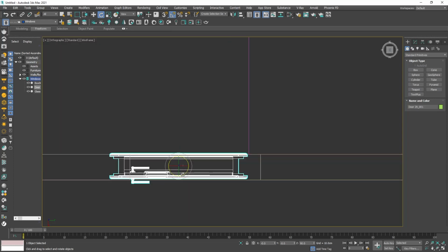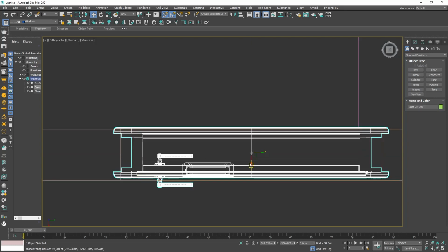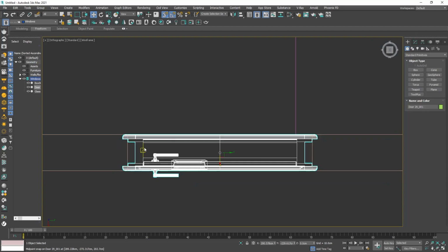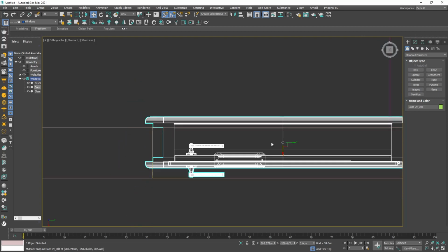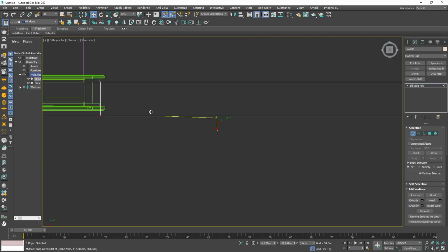Unfortunately, the door width is not the same as the wall, so in that case, we can tweak the door geometry or the wall depth. Since it's a simple tutorial, I will do the second. Enable the vertex poly mode and move the vertex to change the wall width.